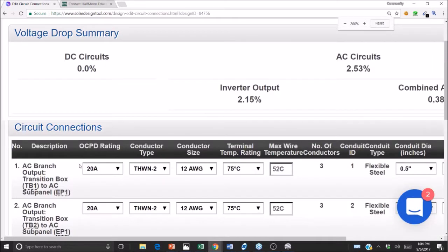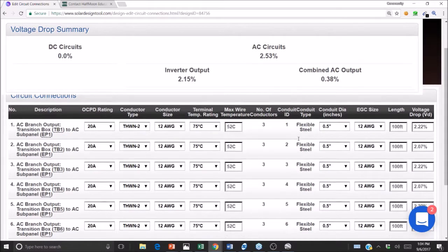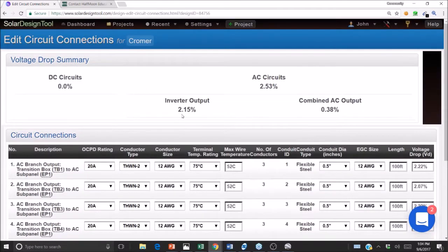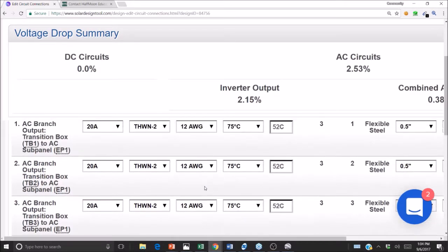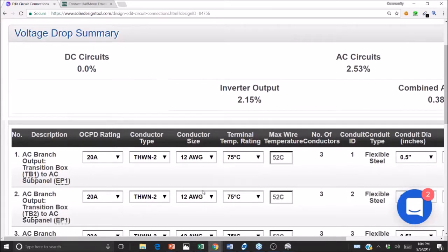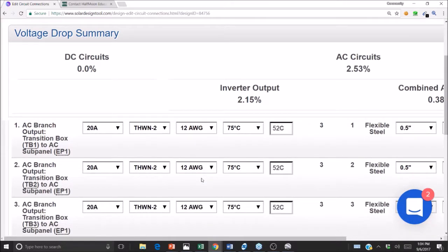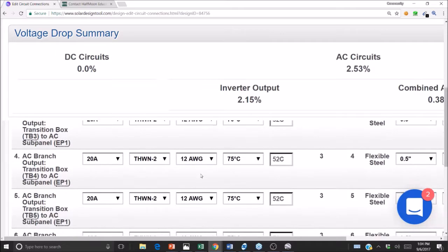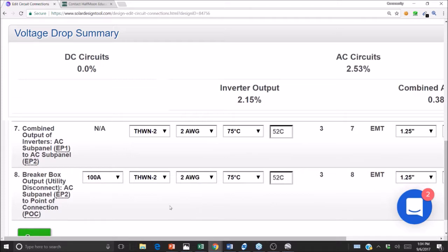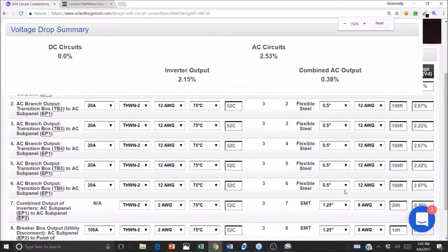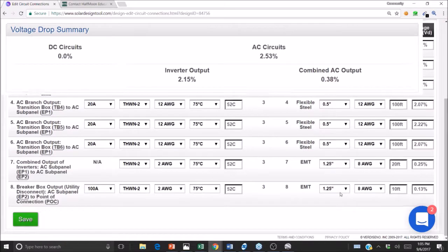And you can't rely on software alone, but then again, it does make a heck of a guess, as guidance. Like that in-phase microinverter cable is number 12 AWG, and it has a junction box that only takes number 12 AWG. And so what I'm seeing is it's all right. It's within range to do number 12. And then I'm in number 2 when these things combine. I'm looking at my conduit. It's all 1/2 inch, then 1.25 inch. All this stuff is fine.